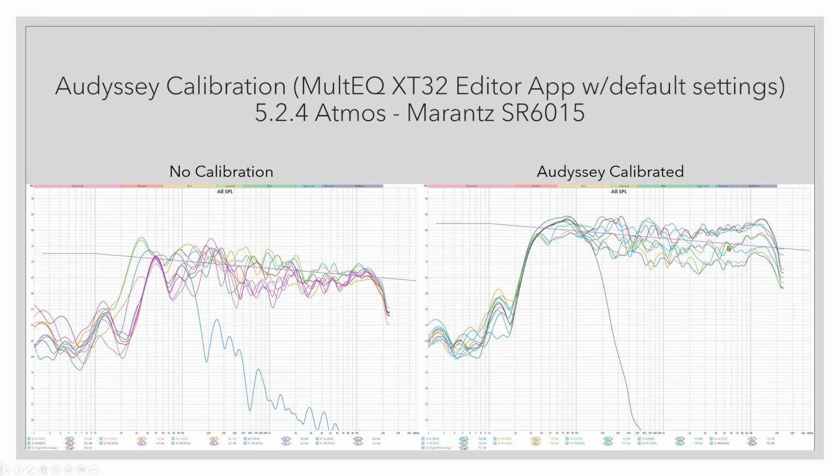Dynamic EQ will keep applying the boost up to 0 dBFS, okay? And 0 dBFS has 200 times more sound energy and is more than 3 times louder than the 85 dB reference level, and will quickly cause permanent hearing loss if you're exposed to it. It's hard to understand Audyssey's choice to hold dynamic EQ boost all the way up to that level. When comparing filters, we tend to think the louder filter is better for the first few seconds, so maybe excessive loudness is an Audyssey trick to make an impression.